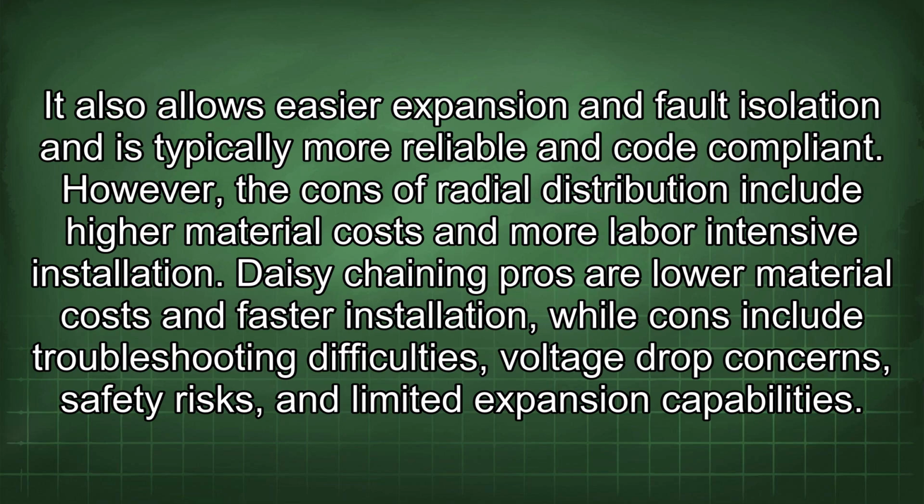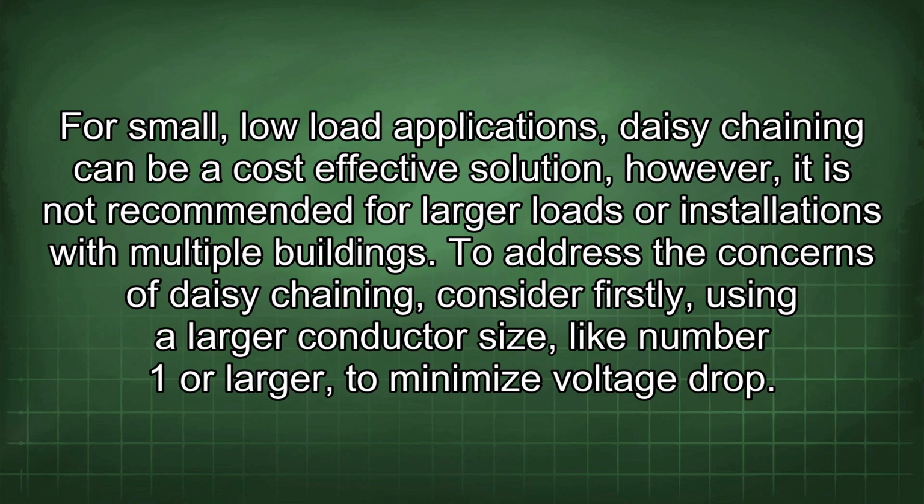Daisy chaining pros are lower material costs and faster installation, while cons include troubleshooting difficulties, voltage drop concerns, safety risks, and limited expansion capabilities. For small, low-load applications, daisy chaining can be a cost-effective solution. However, it is not recommended for larger loads or installations with multiple buildings.